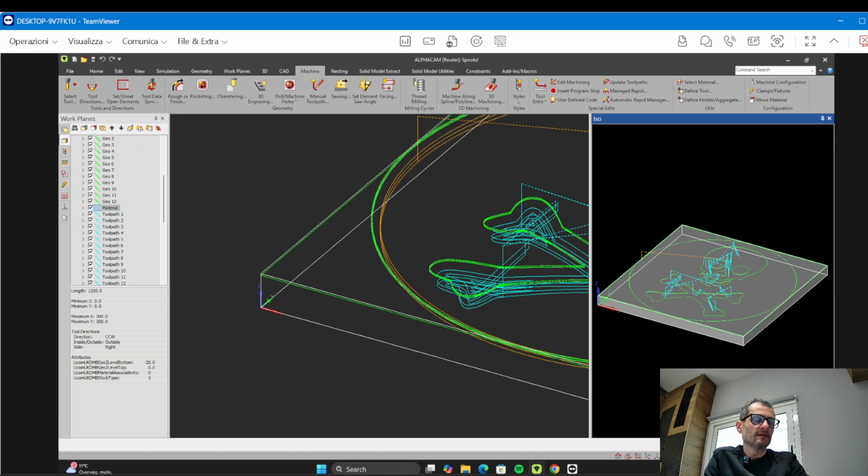Okay. But like a 3 millimeter router, for example. Yeah, of course, 3 millimeter diameter, you have to go down. It depends about the material also. I cannot say one measure or another one. It depends. What is the material that you are using? It's no strong wood. It depends, because if it's strong wood, it depends about, I repeat, so it can be with 3 millimeters you have to go down very slowly and you will break a lot of tools, because 3 millimeter is not the right choice. In woodworking machinery, 3 is too little, in my opinion.